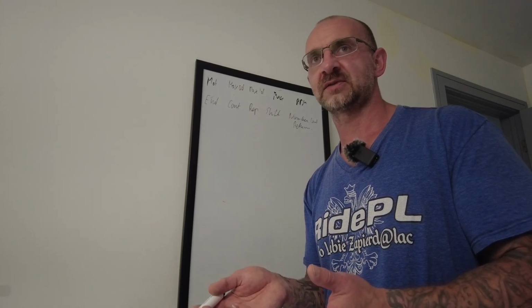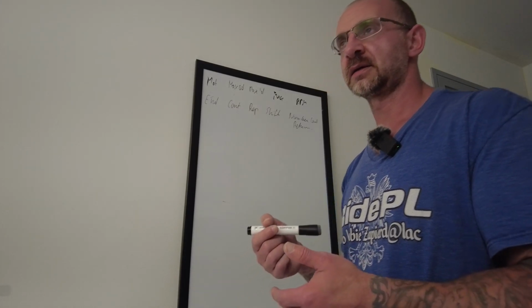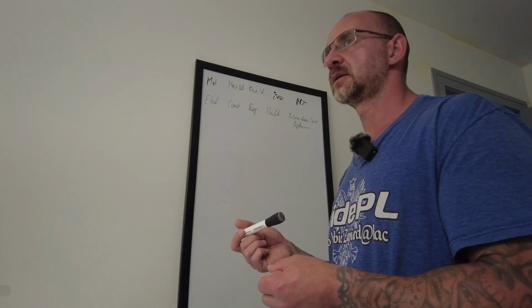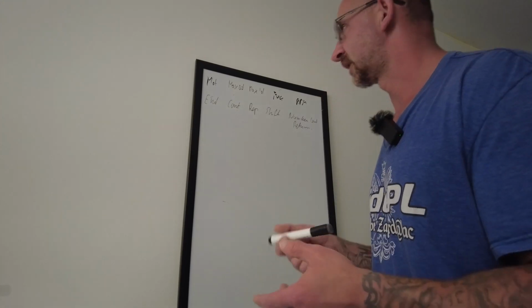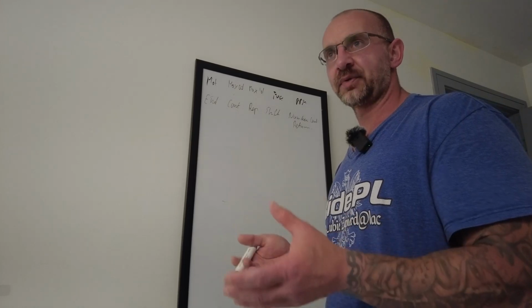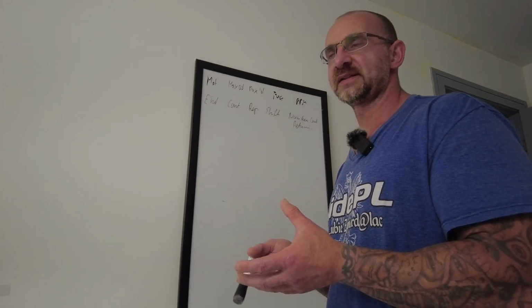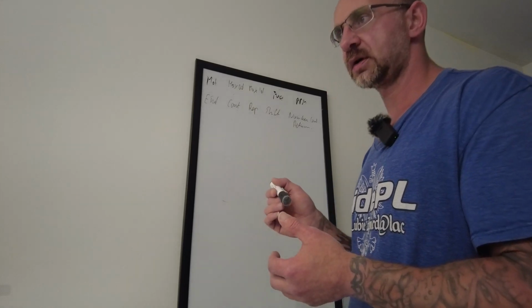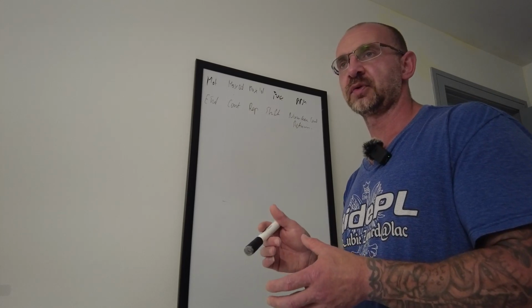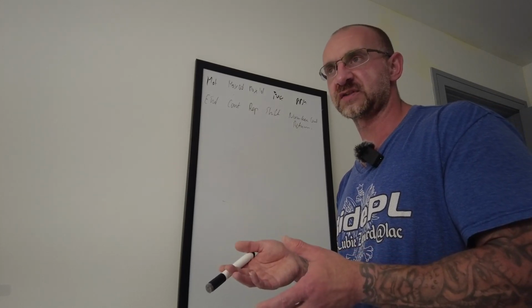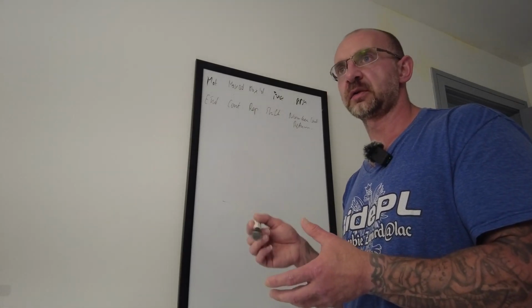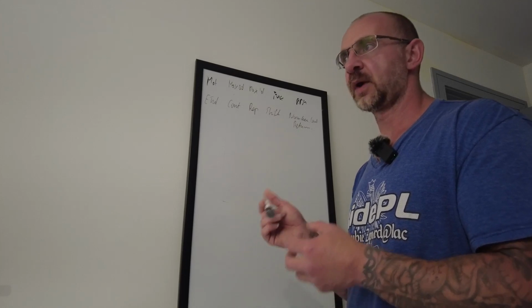It takes a fraction of a second to make the adjustments on the fly, and you're gonna get more comfortable with that the longer you machine, right? Now, max OD. So, for example, I have a 2-inch part. I'm gonna put, let's say, 6 or 8 inches. I always go bigger. The thing is that if you have a 2-inch part, you cannot put 1.8 inches, for example, because, and I'll explain in a second, I'll always go a little bit bigger or a lot bigger, and why?